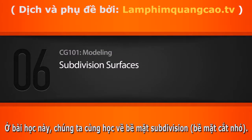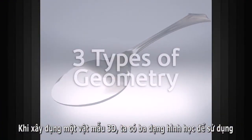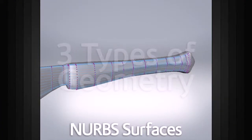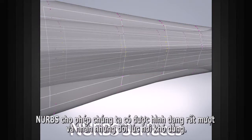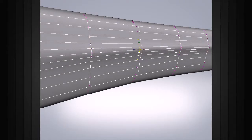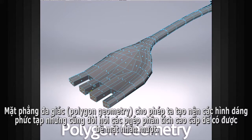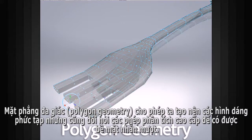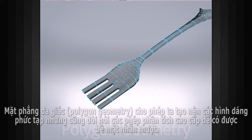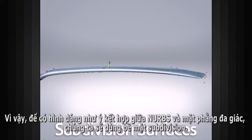In this lesson, we will learn about subdivision surfaces. When building 3D models, there are three main types of geometry that we can use. NURB surfaces allow us to get very smooth shapes, but can sometimes be more difficult to use. Polygon geometry allows us to create very complex shapes, but high resolutions are actually required to get smooth results. So in order to get the smooth shapes associated with NURB surfaces, combined with the flexibility of polygons, we will use subdivision surfaces.